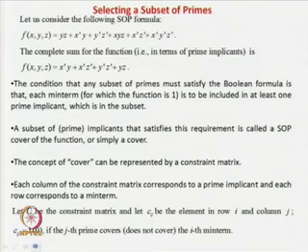You have to find the proper subset so that it covers all the terms. It is a subset covering problem, and if you look at any theoretical computer science book, you will find that the subset covering problem is an NP-complete problem, which is very difficult to solve. There is no well known polynomial time algorithm to solve it. So again we go for some heuristics, which we will see later. Overall the problem is a subset covering problem, because given some prime implicants, you have to find a proper subset which covers all the min terms.